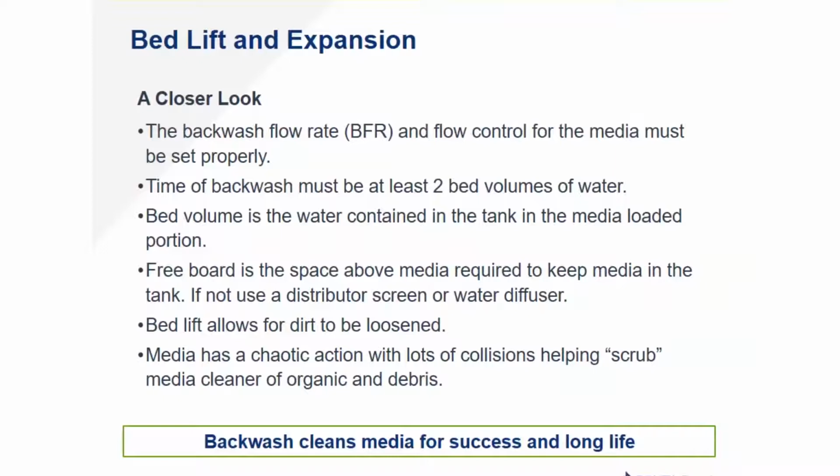In one of the seminars I went to on cation exchange resins, OEM manufacturers of cation exchange resins say backwash is the most critical step to the regeneration process, because if you can't get the dirt and the grime off of the resin bead, you can't exchange it, and you'll start to lose capacity very, very quickly.